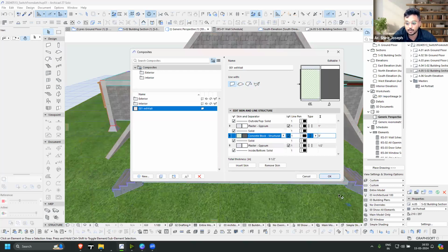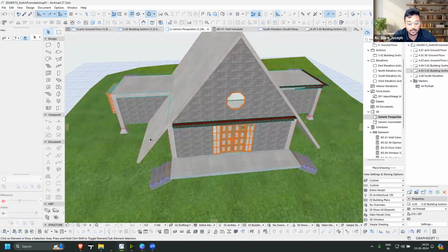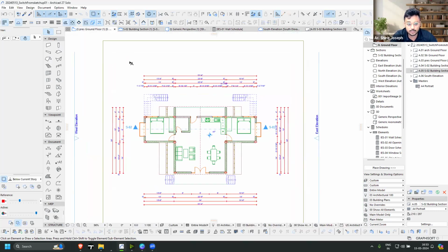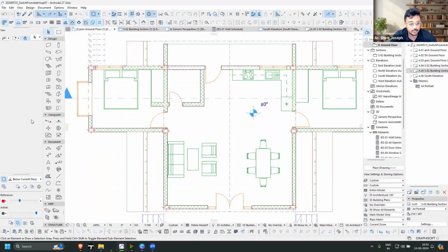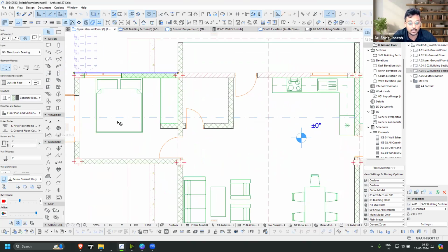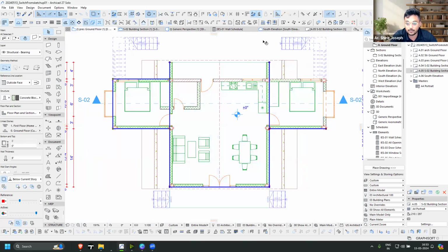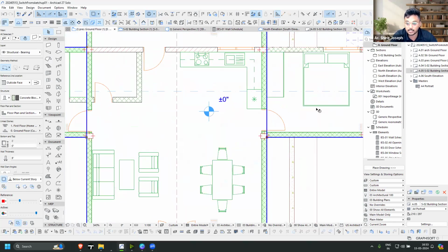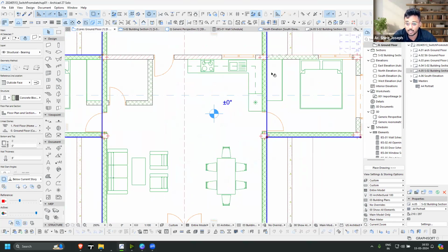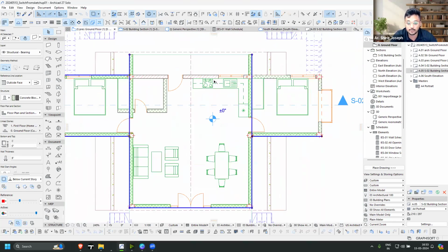So a good practice would be that. And I'll just give OK. Now, how we are going to change from here is, all these walls right now, if you notice, this is an 8-inch wall itself. So we can just select all the external walls which need to be converted to this plastered wall. So if you have divided this into internal and external separately, it will be much easier. You can even work on having both the plasters on that specific dimension.